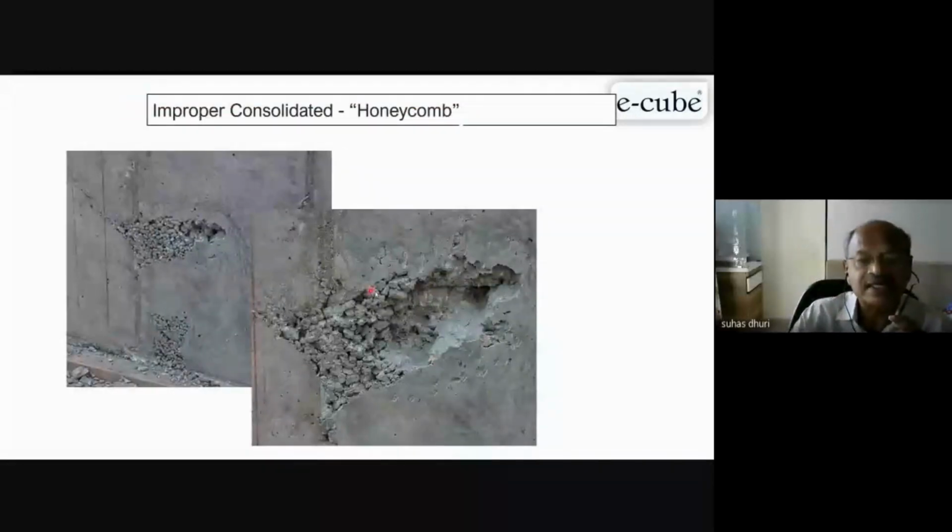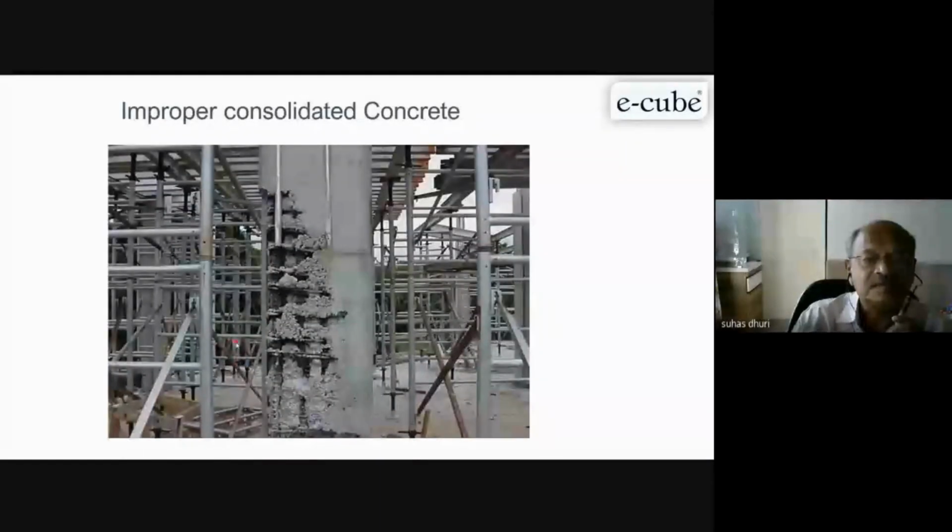Otherwise, you will get this, not reached. See, honeycomb like this will come because vibration has not reached that particular level. See this.